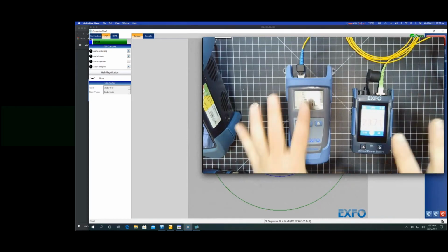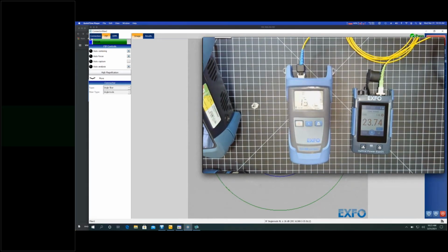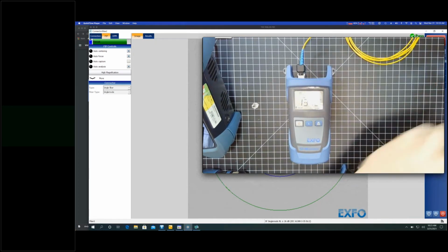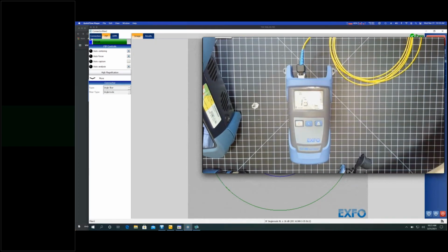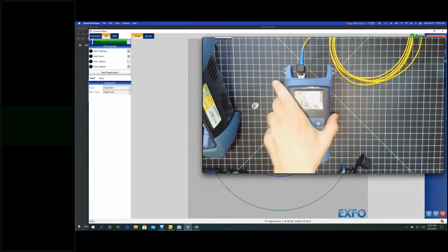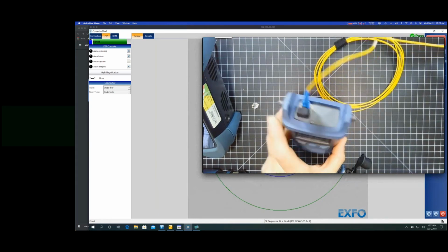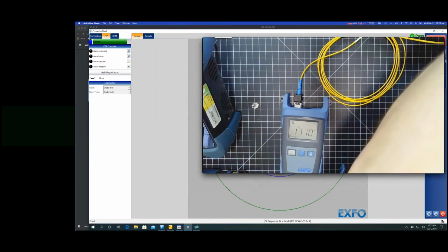So now that I've got, we'll say, call this fiber 1, A to B, now I would physically move my meter from this end of the test, in which case I'll need to change and re-reference, because now I've got an SC-UPC cable to an SC-UPC at the customer prem. And then on the other end, I'll have an SC-APC.